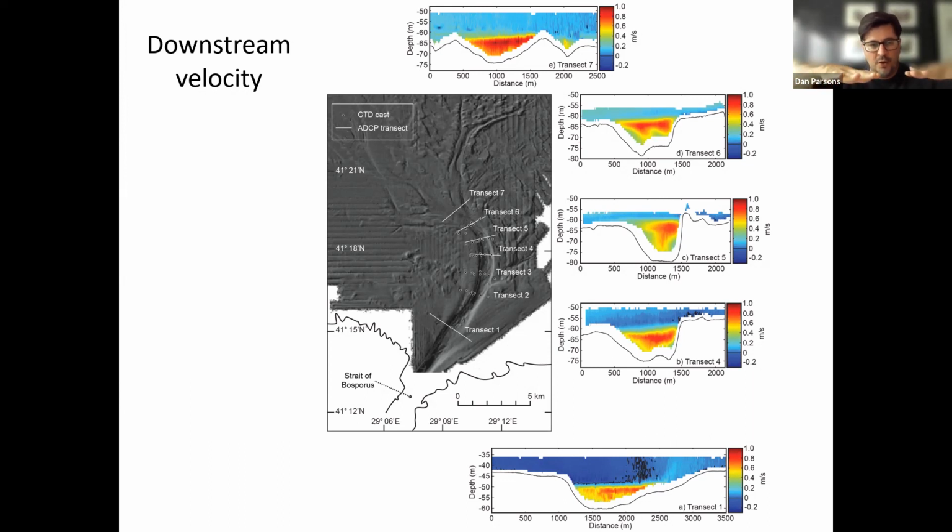And that's because the water, as it goes into a bend, has the outward forcing centripetal acceleration, or the centrifugal acceleration essentially, that tilts up the flow as it goes round a meander bend. And as a result of the pressure gradient force that's created there, you have a return flow near the bed that results in this helical flow that's outward at the surface and inward at the bed. And that's classical bend flow theory, going back to Leonardo da Vinci's drawings.